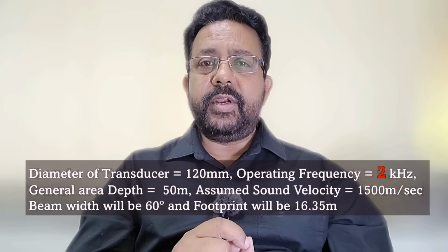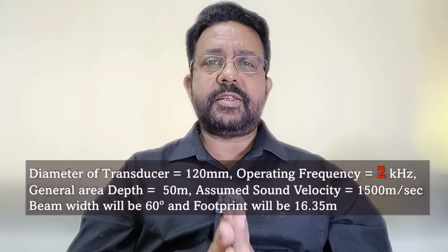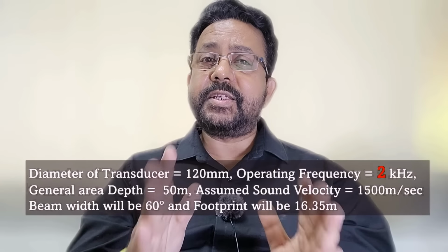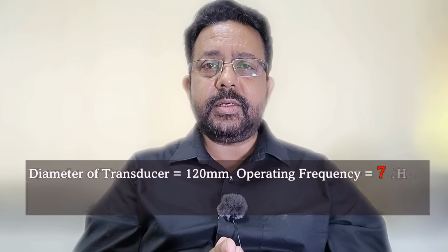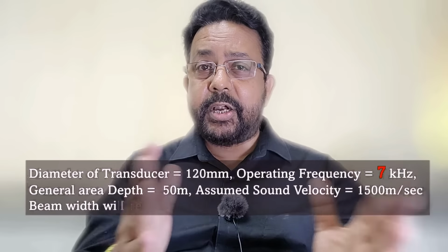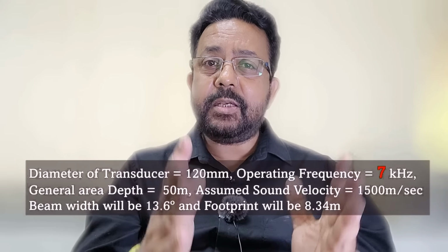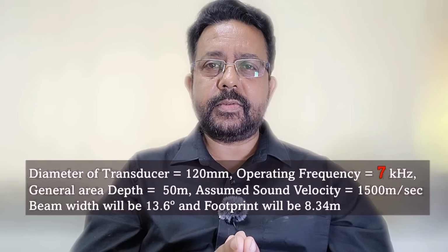Then your beam width is going to be just under 60 degree and your footprint on the seabed will be 16.35 meter. Now if you change your frequency to 7 kHz, the beam width will be 13.6 degree and the footprint on the seabed will be 8.34 meters. You can use this formula to calculate your beam width and footprint.